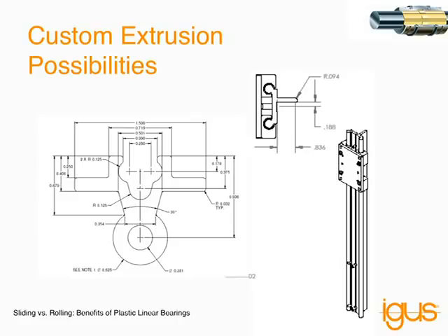aluminum extrusions. These profiles offer a lot of flexibility and a lot of customization. Usually plastic linear bearing manufacturers like us utilize specialized extrusion mills that are able to produce extrusions to about 1/5 of the standard commercial tolerance. But one really unique thing that enables a lot of designers a real lot of value is the fact that you're able to design profiles for linear plastic guides.